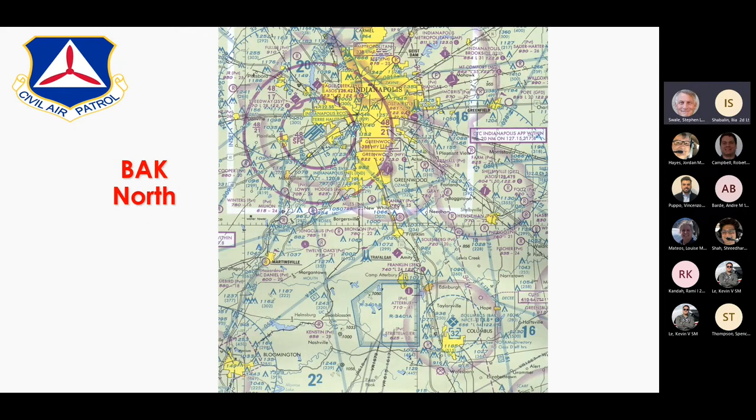Oh, I wanted to say one other thing. The last objective on that slide talks about going to the National SAR plan, which is interesting. The acronym is IMSAR. That has been revised recently, and the supplement that they're talking about is now called the area. You'll also see magenta airports, all the little circular symbols with what are runway orientations are uncontrolled airports. They're in magenta. The blue ones are airports that have continuously operating towers, or if they're not continuous, then the actual operating hours will be in the AFD, the flight supplement.